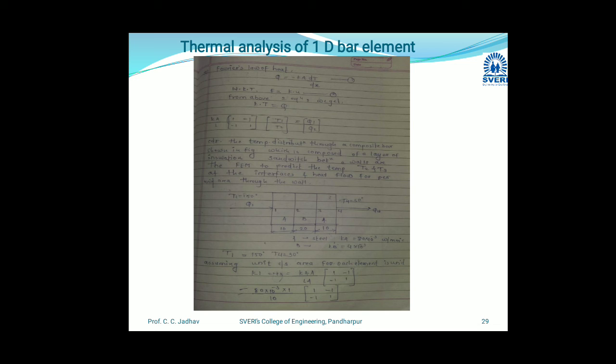So we will get the global matrix, capital K is equal to 10 raised to minus 3 into the 4 by 4 matrix: 8 minus 8 0 0; minus 8, 8 plus 0.2, minus 0.2, 0; 0, minus 0.2, 0.2 plus 8, minus 8; 0 0 minus 8 8. So this is our global stiffness matrix for this composite wall problem.